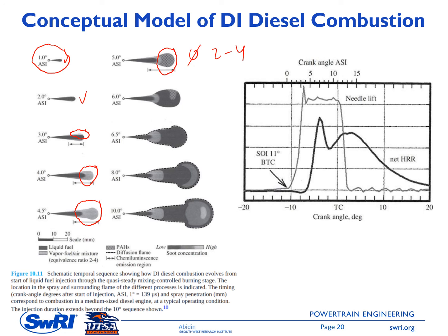then this spontaneous ignition generates a spike of heat release here, and then at further crank angles you still see the premix combustion, and then this premix combustion is followed by the diffusion flame. This diffusion flame occurs at the periphery of the spray, so this dash line.